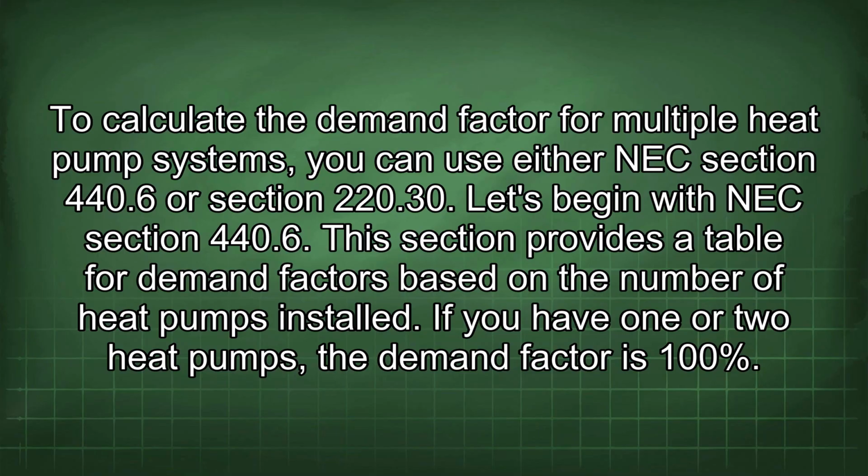To calculate the demand factor for multiple heat pump systems, you can use either NEC section 440.6 or section 220.30. Let's begin with NEC section 440.6. This section provides a table for demand factors based on the number of heat pumps installed.